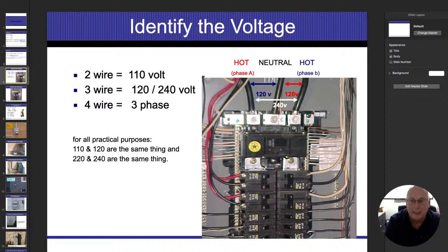I mentioned before appliances such as well pumps and central air conditioning systems and electric radiant baseboard heat. Those don't require a neutral. But let's say I hit an electric stove or electric dryer. Those are also 240 appliances, but with those appliances, I actually need a neutral wire. The reason is because I'm going to end up having 120 light bulbs in there, maybe a 120 computer. So that's only going to take power off of one side. It's not going to be equal on both sides. Because it's not going to be equal on both sides, now I have to have a neutral bringing down the difference. So we're going to end up with 2 energized conductors, 1 neutral conductor, and we should also have a grounding conductor just in case we get a phase fault or something happening there.